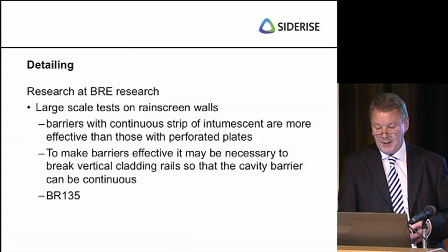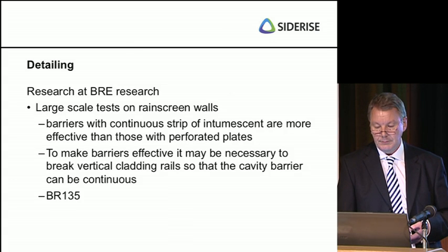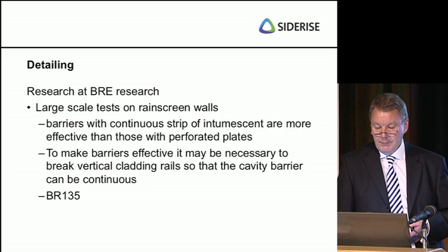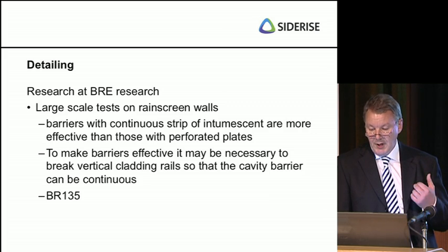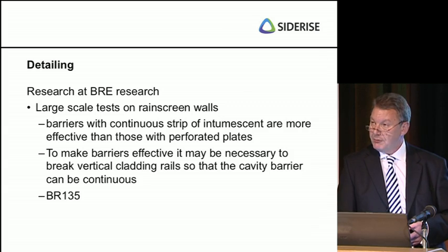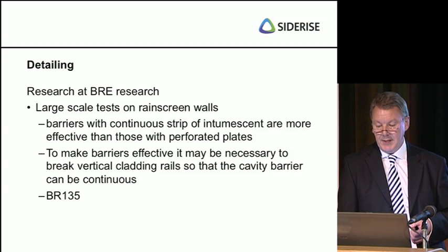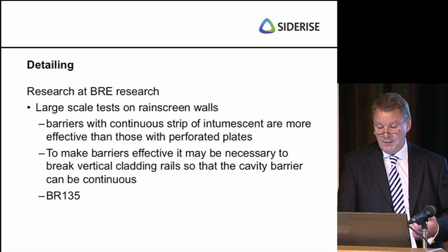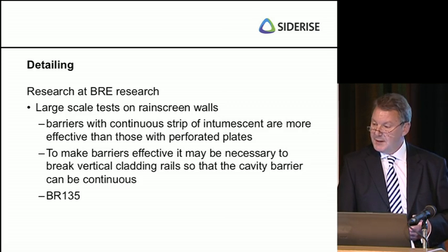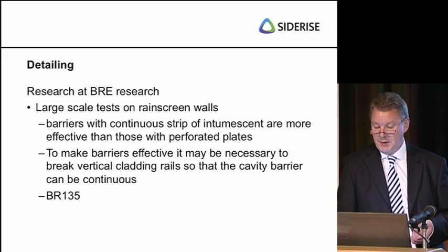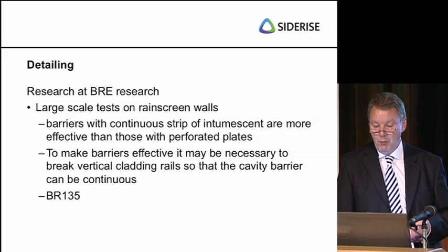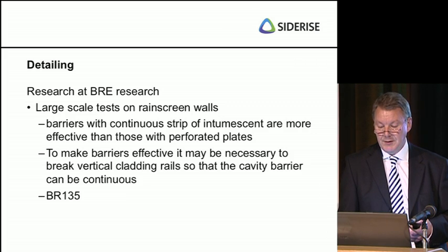Simple concept, effective performance. The concept has been verified by research at BRE using large-scale tests on rainscreen walls, as per the last speaker. Part of that research stated that cavity barriers with continuous strips of intumescent material are more effective than those with perforated plates.